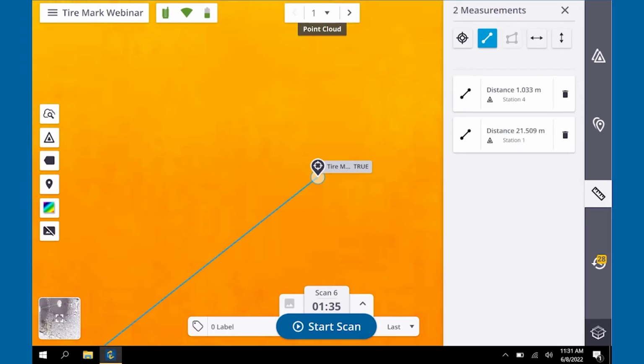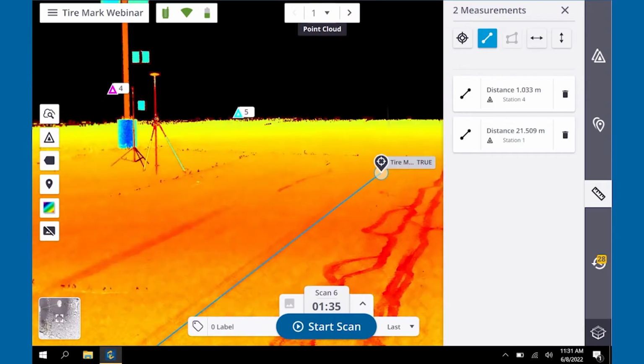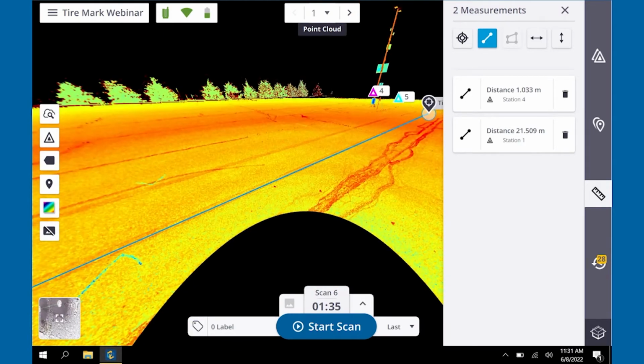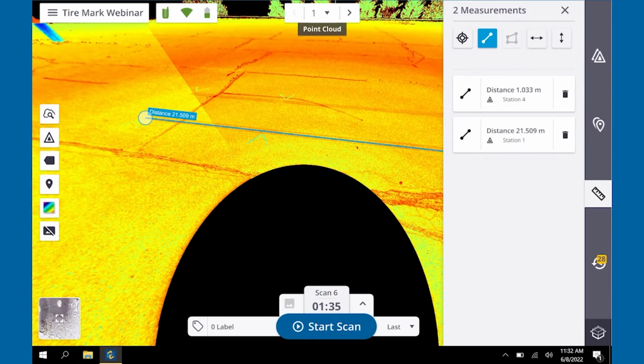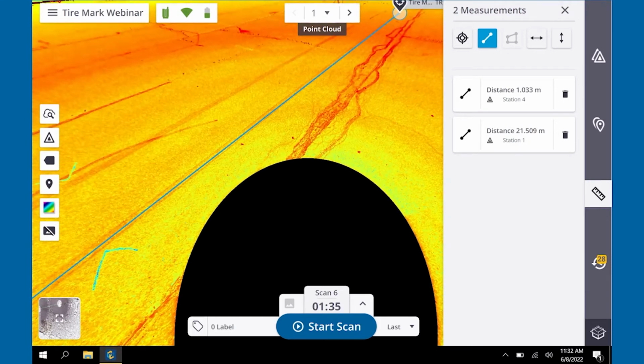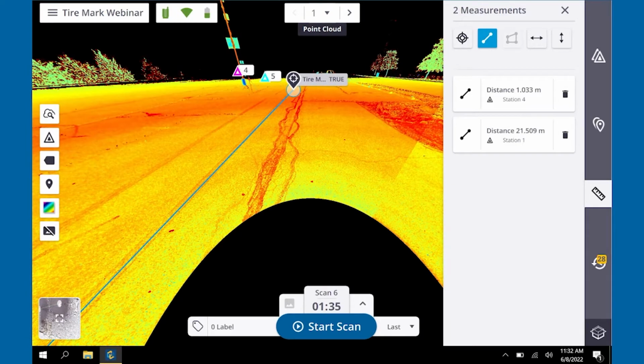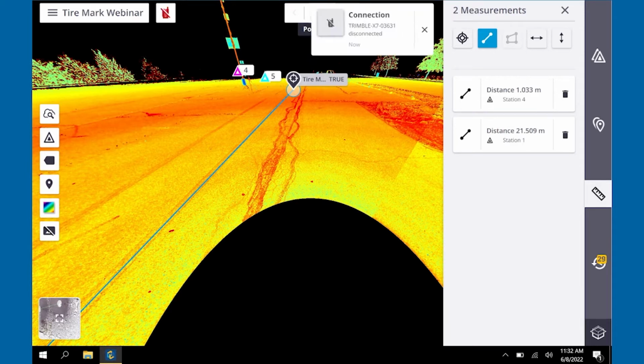And the total length of our skids is 21.509 meters. So we'll just truncate it to 21.5 meters. That's the length of our skids. Again, we're using a drag factor of 0.82. So 21.5 meters of skids, a drag factor of 0.82. Wonder what that is.